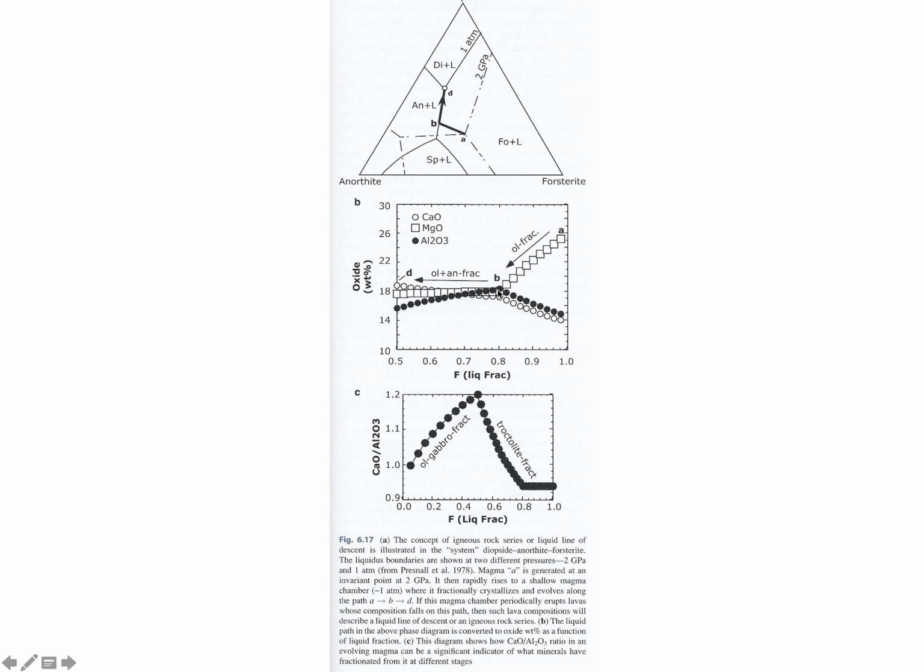Of course, when we are going from B to D, we also have an increase in aluminium oxide because we are forming anorthite here. And that is F, our liquid fraction. Here we have a lot of liquid going from 1.0 down to 0.5, so we are forming more and more crystals out of our melt.